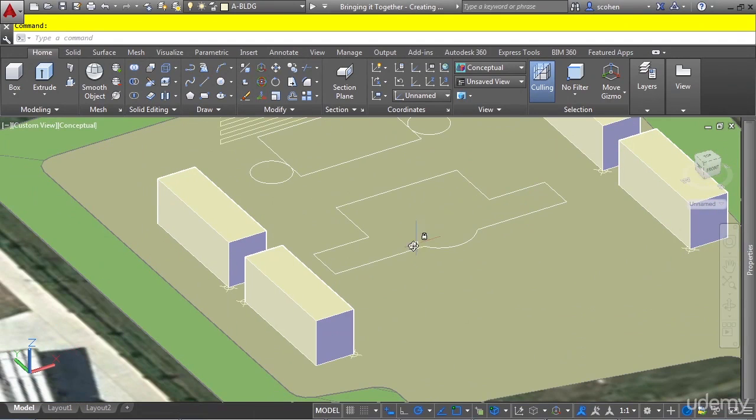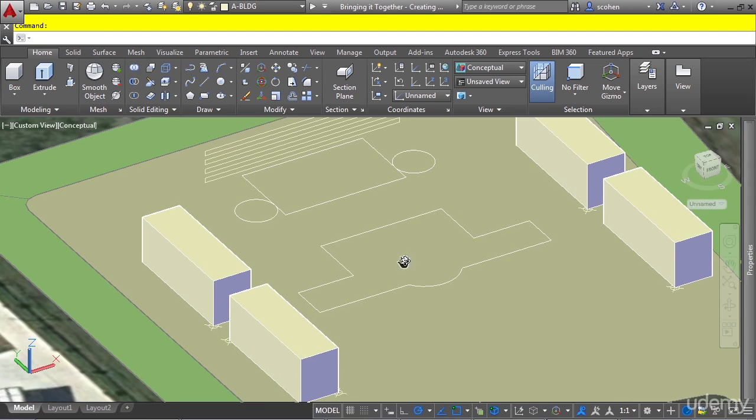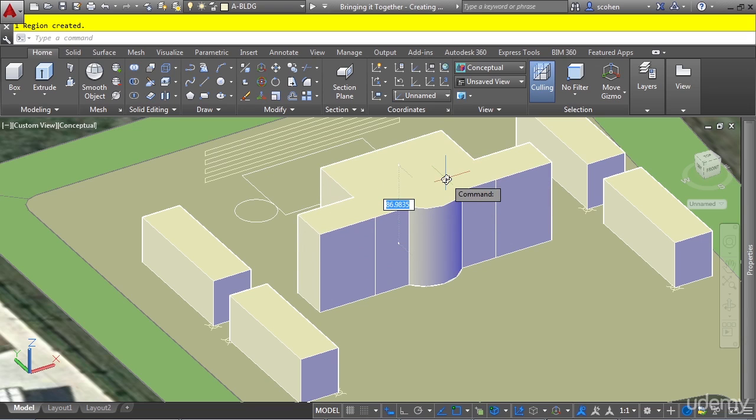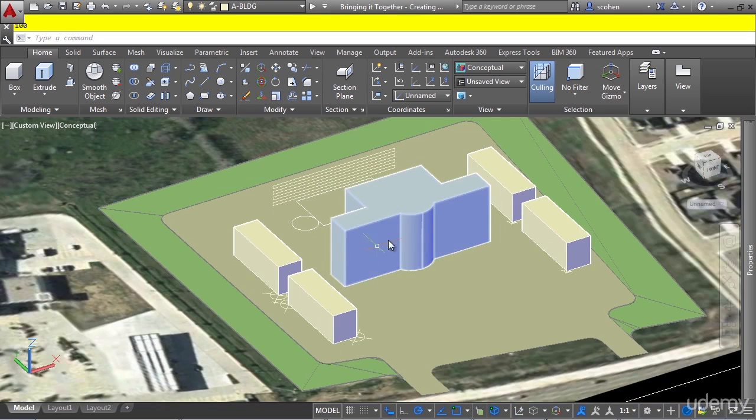Now let's go ahead and press pull our main office building using the shortcut Control-Shift-E. As soon as you hover, it'll highlight the boundary within where your cursor is, and then simply left click. You're immediately prompted for the height. For the height, let's go ahead and type in 100 and then press enter. And there's our initial office building.